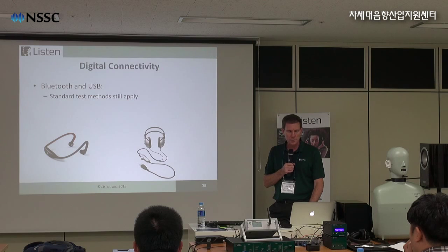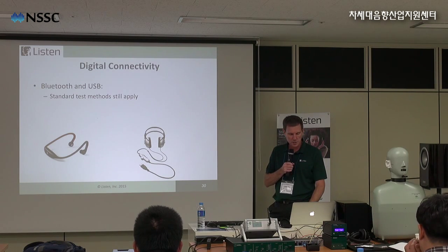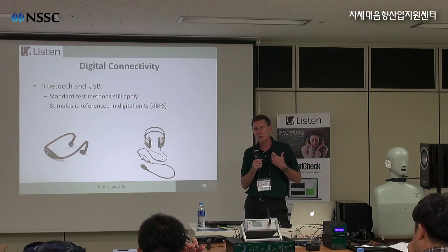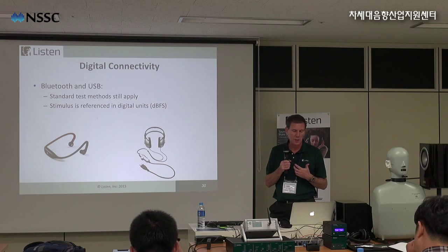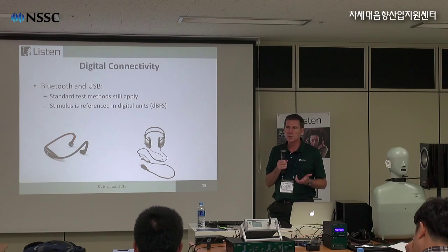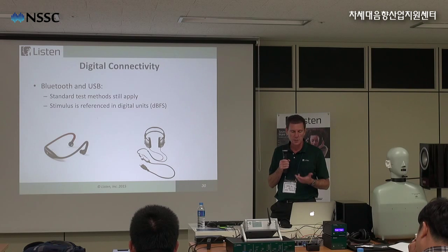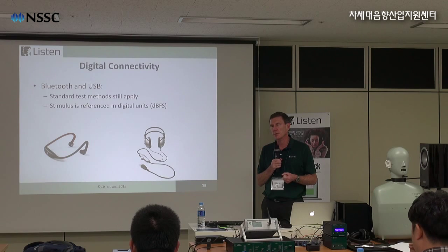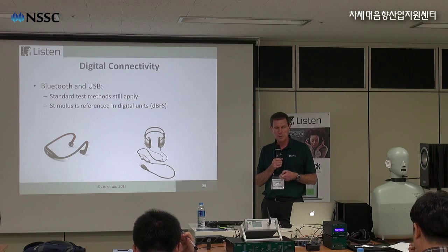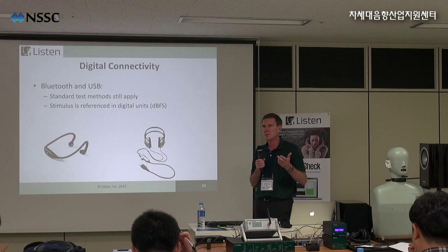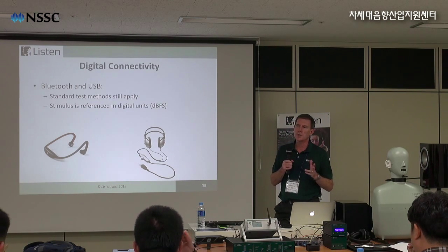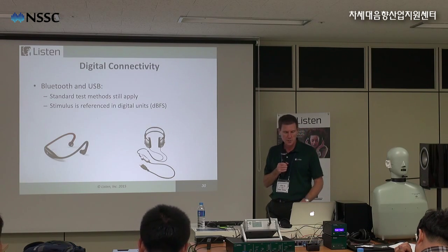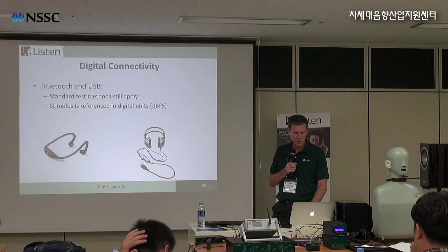You still have the standard test methods, same metrics, but now you have to talk about a digital signal. Essentially, you're going to have some sort of digital in and out, depending on whether it's a headset or just a headphone. And then you have to define the level in dBFS. So instead of it being so many dBSPL with so many volts in, it's going to be so many dBSPL with so many dBFS in. So it's a little different, but it's also quite easy to do.